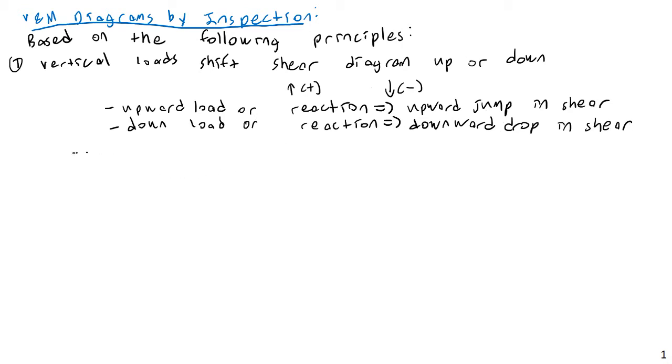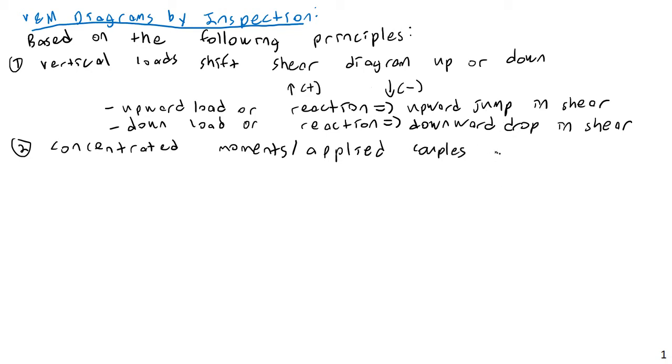Two, concentrated moments cause jumps in the M diagram. Concentrated moments or applied couples, really the same thing, different words for the same thing, cause a jump in the M diagram.